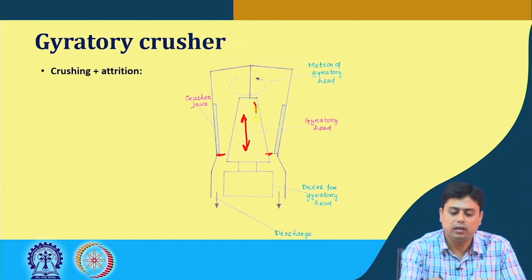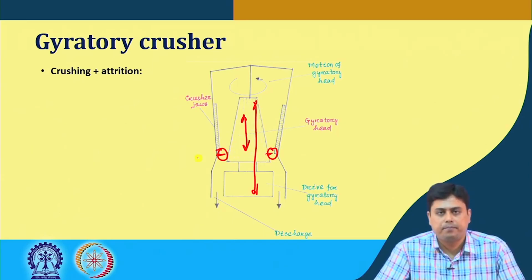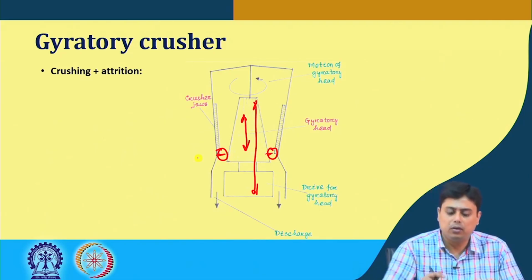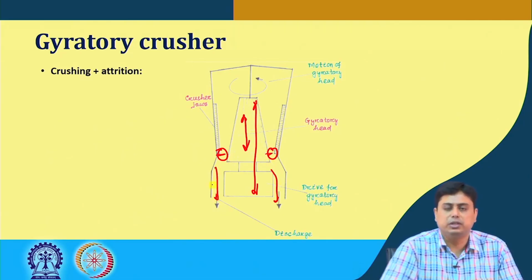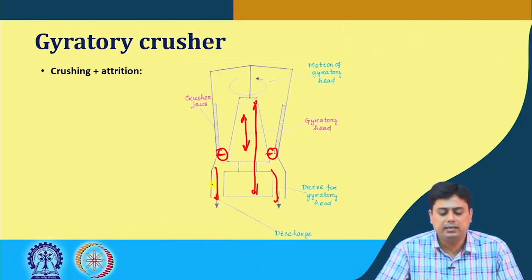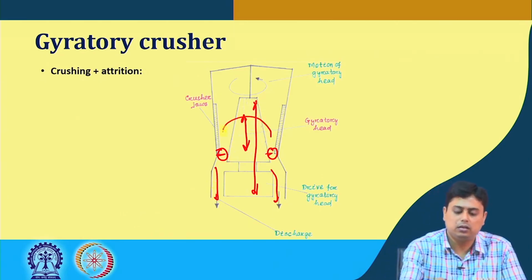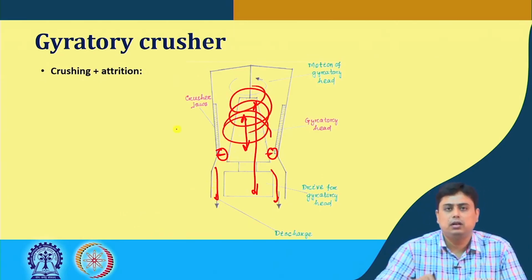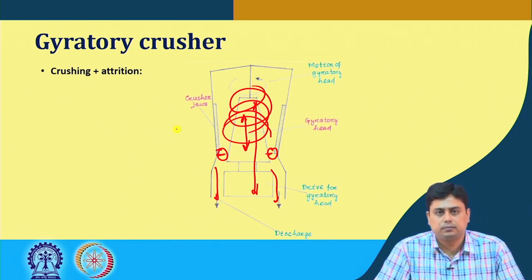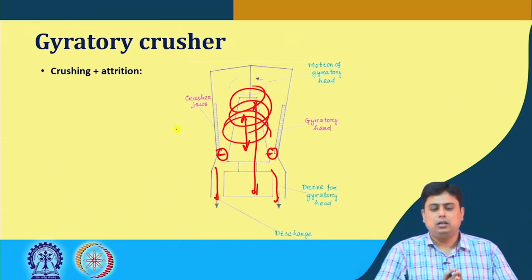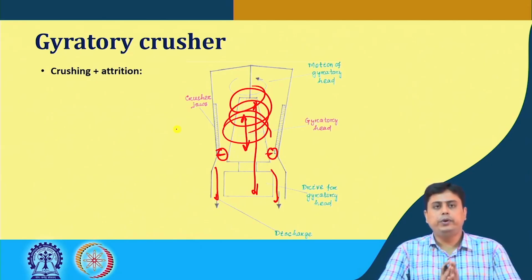So this whole thing can be adjusted to set this gap. The particles of sizes lesser than this gap will come out from this chamber. Until that happens, it stays in the chamber and the crushing goes on. So one thing is very clear, that this size reduction process of handling solids is very prone to wear and tear.